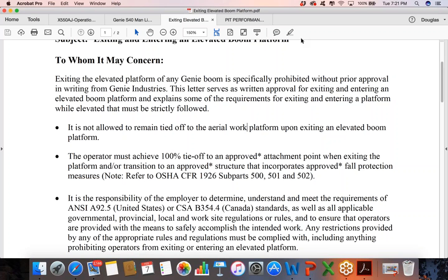Also, clothing materials. Because of flying parts, sparks, intense heat, slag from cutting, grinding, welding activities, clothing can't be made out of polyester or other synthetic fibers. Making sure that we're wearing preferably FR clothing, but if it's not a requirement to have fire resistant rated clothing on, then at a minimum have something made out of, let's say, cotton or a wool blend. Something like that would be more resistant to sparks and be less of a flammable risk while we're wearing it. Also, not having anything with cuffs or flaps on it, right?